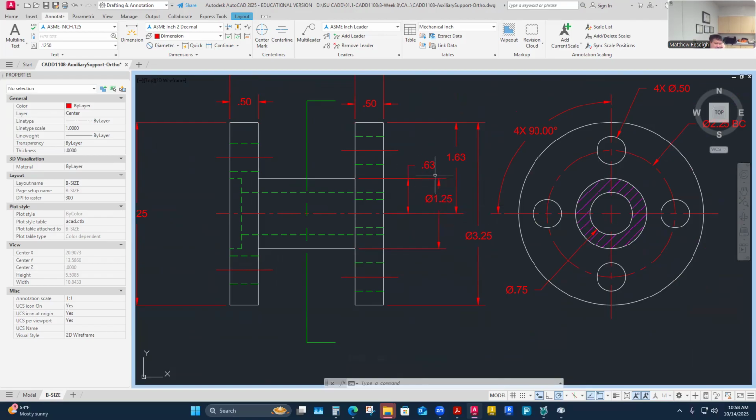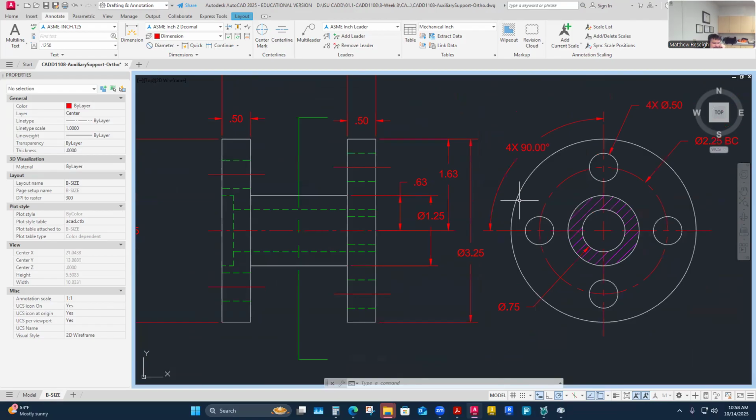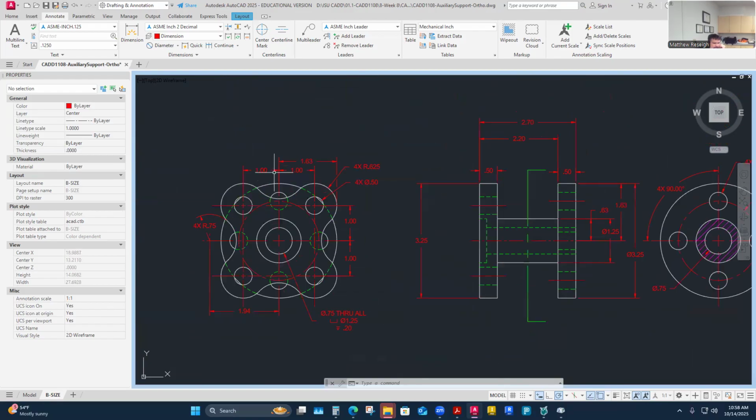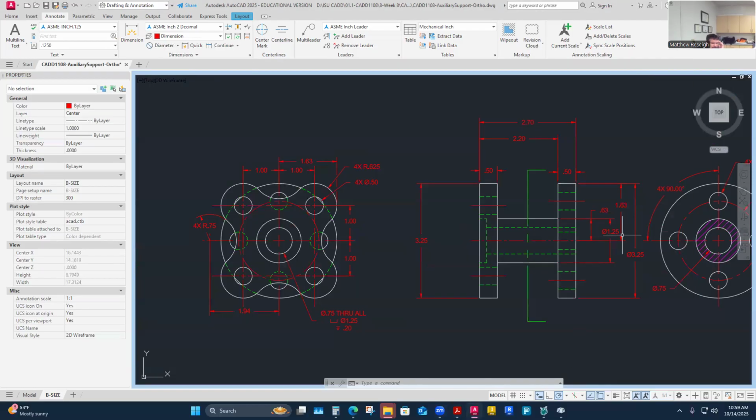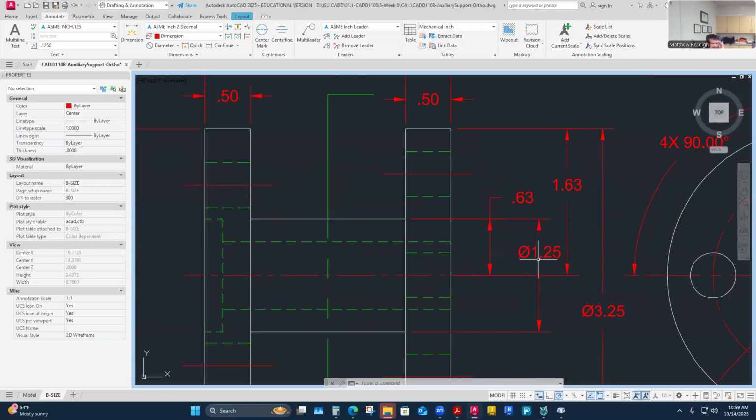And then we'll come back and look at accuracy because right before Nathan left, he did say something that stood out to me. Is like, well, if I'm snapping these dimensions, do I need to make sure that I don't have some inaccuracy? I know we've carried 3 decimal places here. That's the only one on the print that was really carrying 3 decimal places. Everything else was two, but there might be some places where that doesn't make sense. What I mean is, does this make sense that this is 0.125 and this is 0.63?